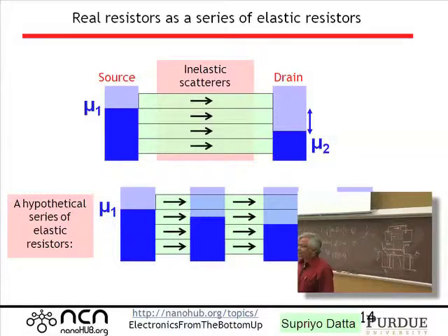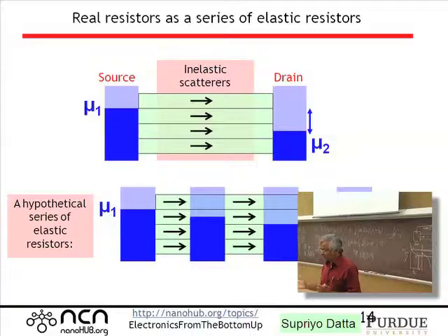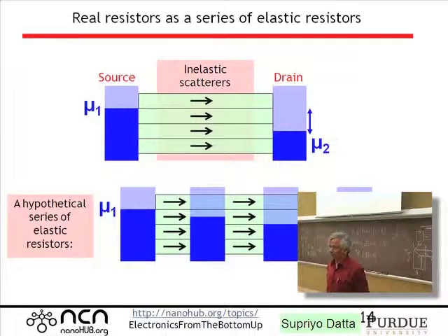If in an electrical resistor you are trying to figure out whether something would be linear or not, whether your Taylor series expansion works or not, I would say that you shouldn't drop more than 25 millivolts across that one little thing. If you're thinking of a very big resistor, then you could easily put 1 volt across the whole thing. You buy a resistor from Radio Shack, you could put 1 volt across it, and it's perfectly linear, 1 kilo ohm or whatever you bought.